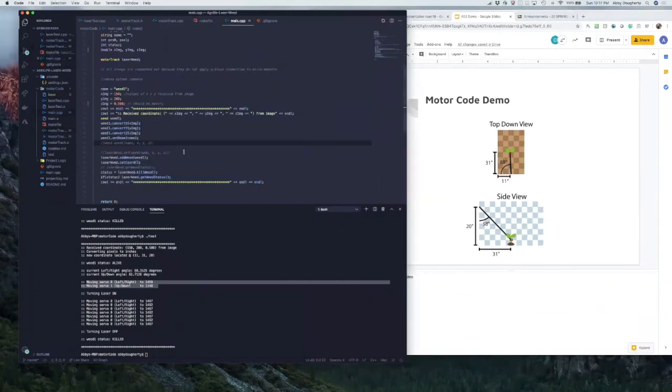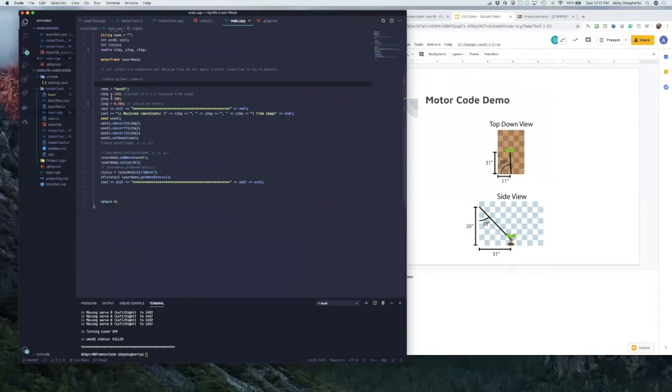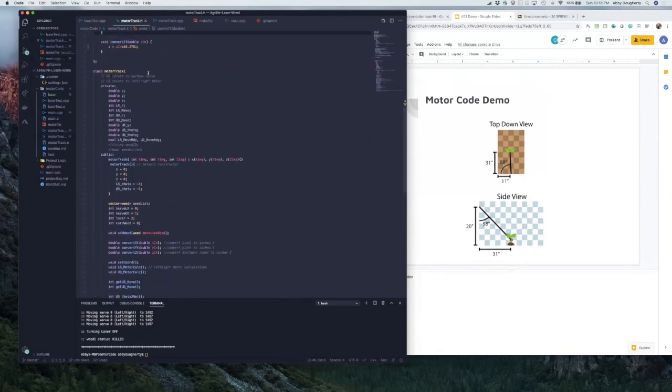If you look at the code, the first thing it does is take the X image, and we're going to get pixel values X and Y from the camera, and we're going to get a Z value in millimeters, how far away the weed is from the top of the frame. And then those will be converted with simple multiplication into inches.